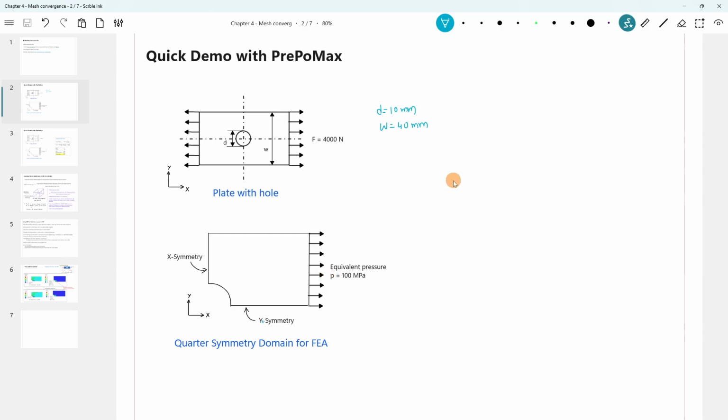Another thing to note, we are not going to do a 2D analysis here, because we want to understand tet elements, which are most popularly used in most projects. So we will start with the simplest element type, that is tet. Why not tria? Because we cannot model tria elements exactly in Calculix.